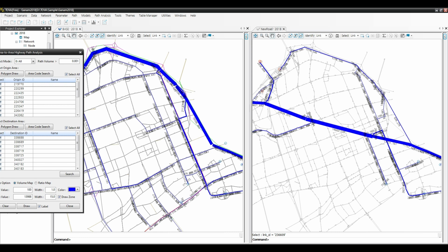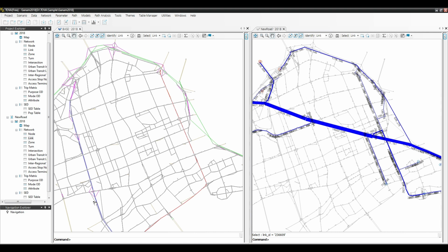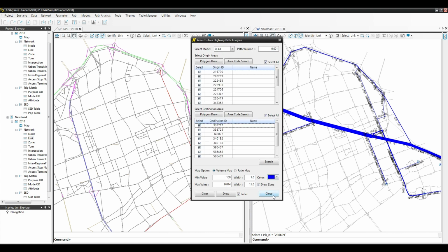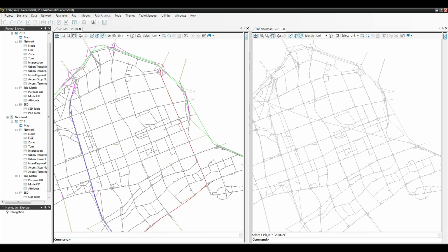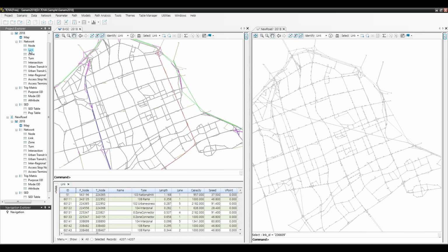Network validation is the process of adjusting various model parameters in a transportation model to make sure that the assigned traffic volumes in the model match the observed traffic volumes as closely as possible for the base year. This is done to ensure the model's accuracy and relevance. To perform this step, it's important to know the observed traffic volume values for major roads. Typically, you can obtain these values from the Traffic Volume Statistical Yearbook.